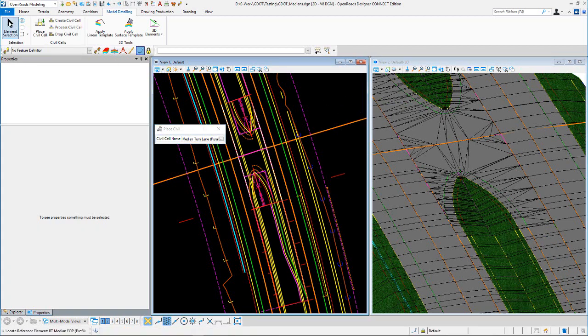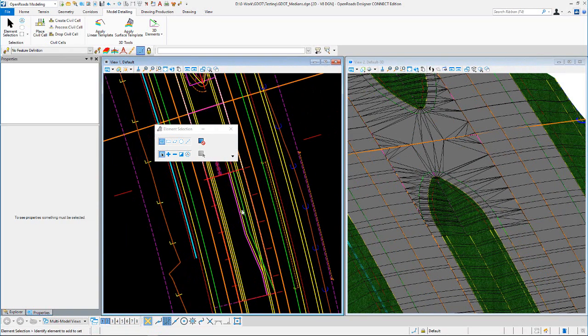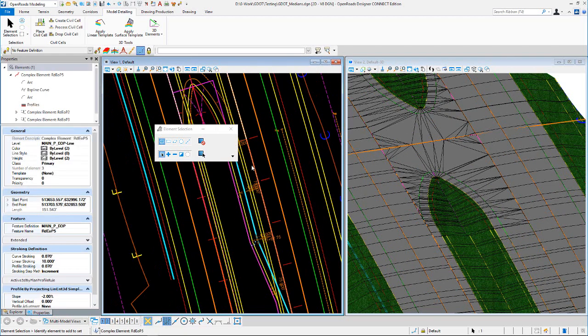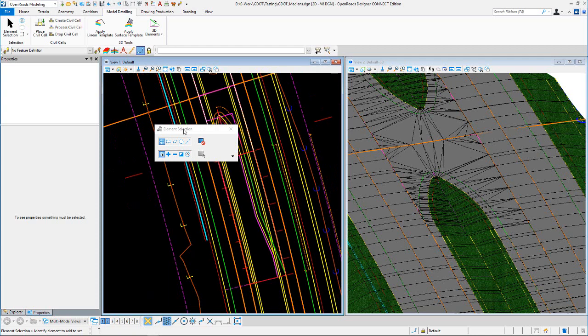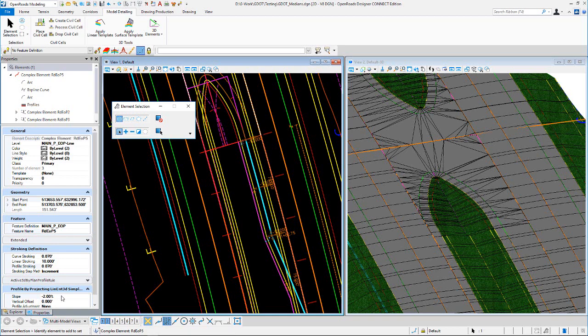Okay, so let's go through some of the edits on this median turn lane here. I think it's pretty straightforward. You just choose the edge of pavement if you want to lengthen your storage or your taper there. As far as vertical, you can see that's just a negative 2% slope projected. So if you need something different, you're in super elevation, and you just use your project tool. Open the profile view of this. Use the project tools to reprofile that.